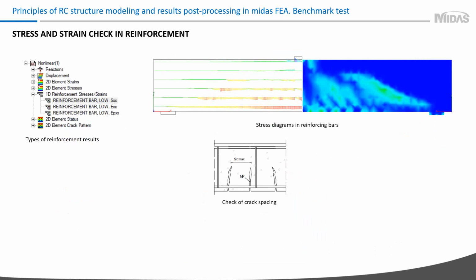So when you do the check of the limit state of your concrete structure, you don't have to check only concrete behavior and check strain and stresses in concrete. You also have to check strains in reinforcement because it could reach a limit.